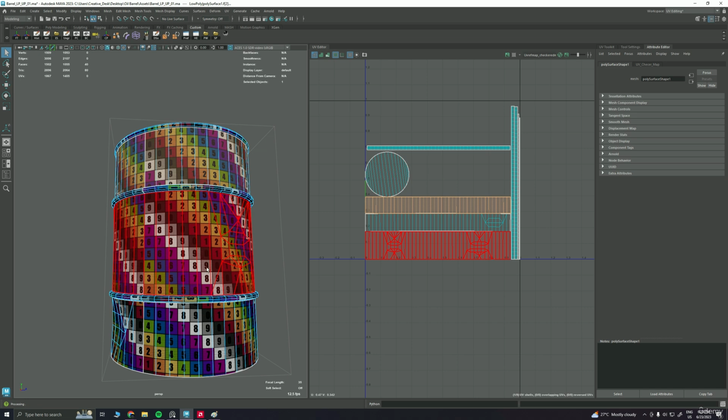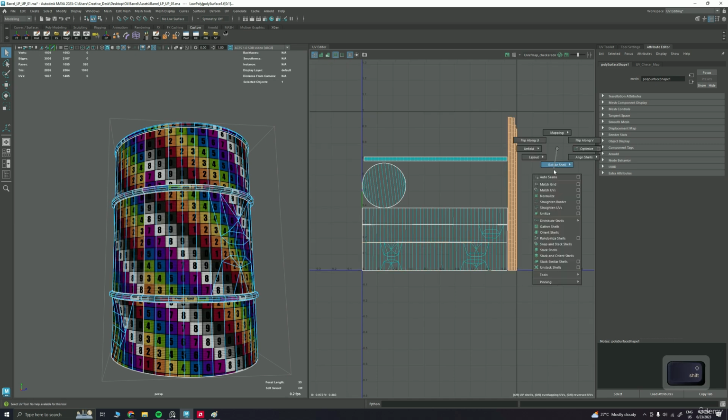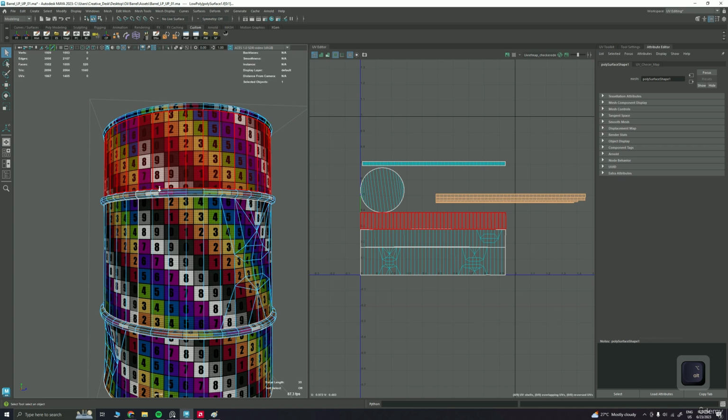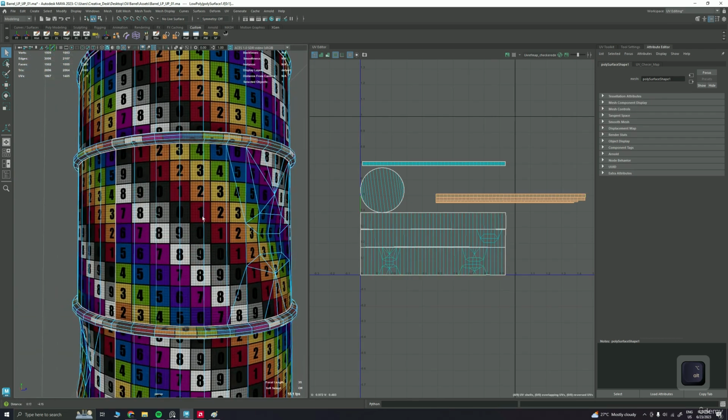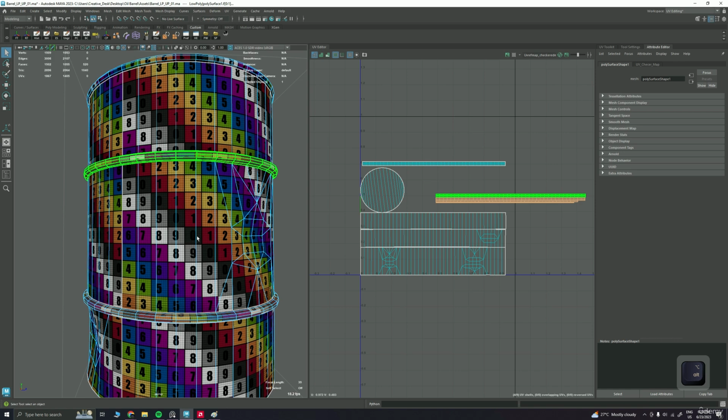So instead of creating inverted textures in Photoshop, what we can do is flip the UVs, so you can create the textures which have text the way they are. You don't have to correct the orientation of these over here because they most possibly won't have any text.